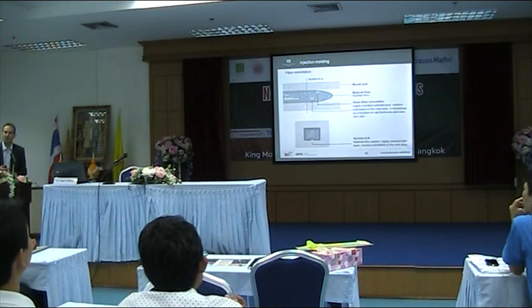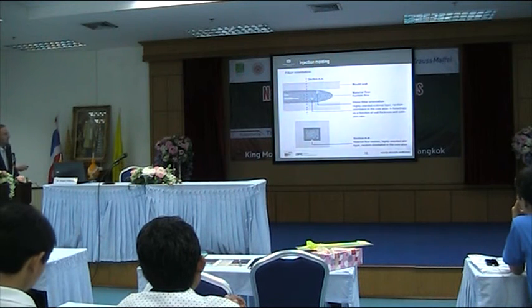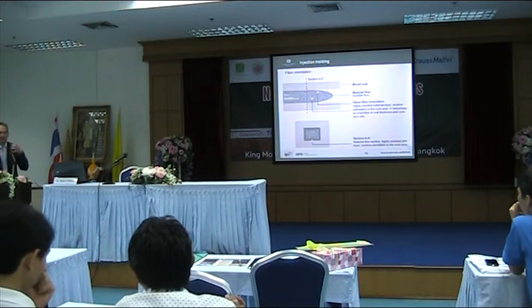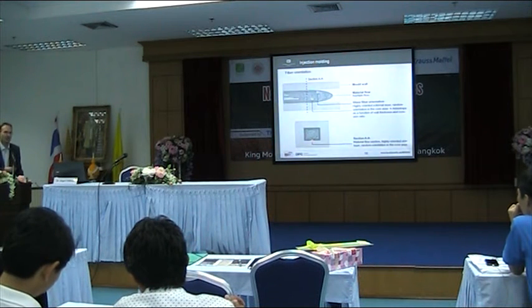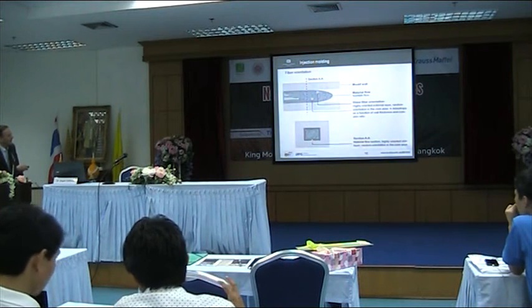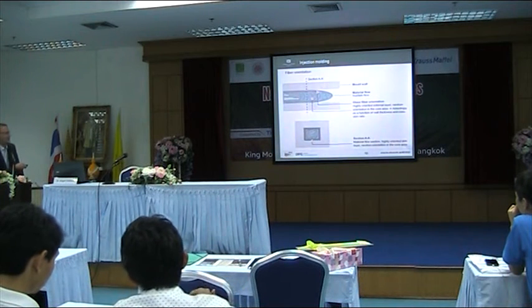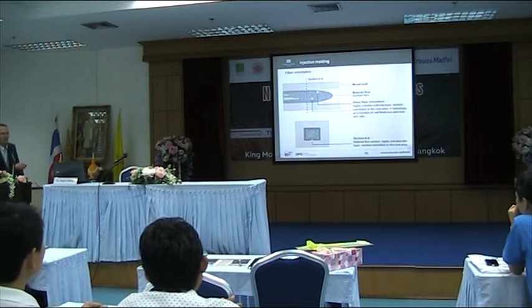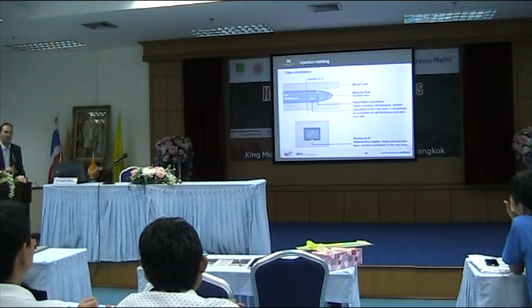You also have, due to the process, a fiber orientation. In the process, you cannot align the fibers as you want for the load. You can play a little bit with the runner system for the part, with making some more runners at specific local positions on the part, but you always have a fiber orientation in the injection molding process with a so-called three layer structure. Normally you have top layers with the fiber orientation in flow direction, and in the middle, perpendicular to the flow.